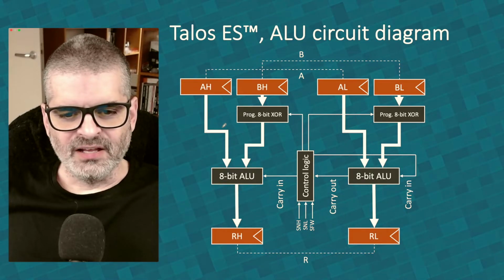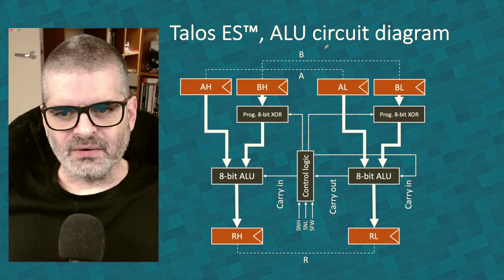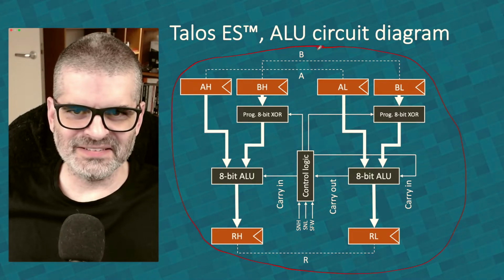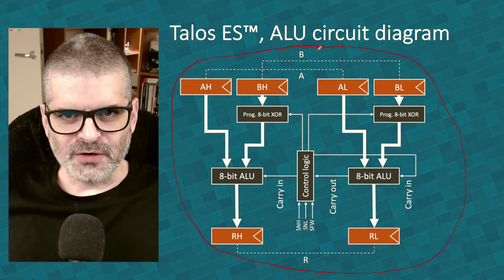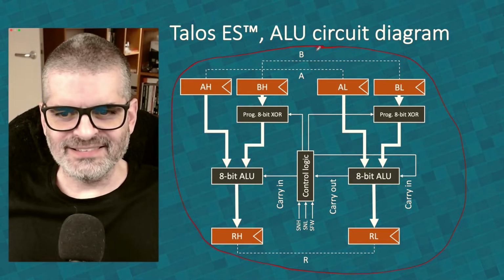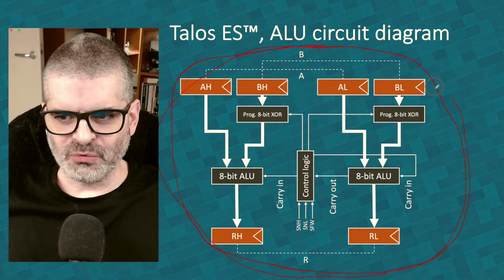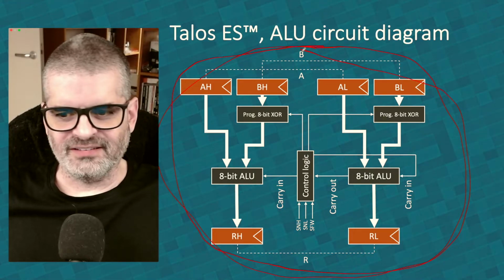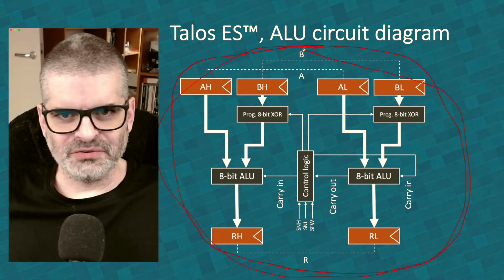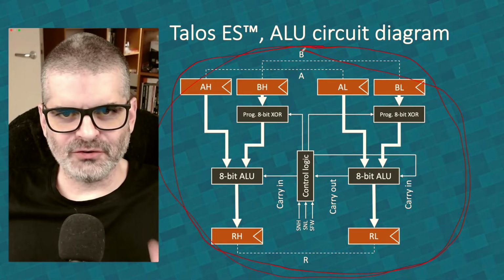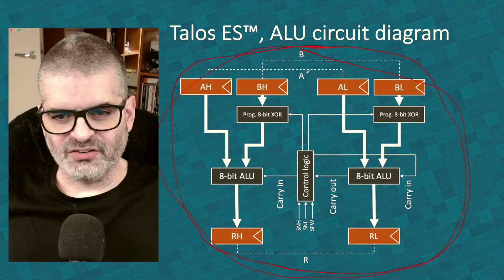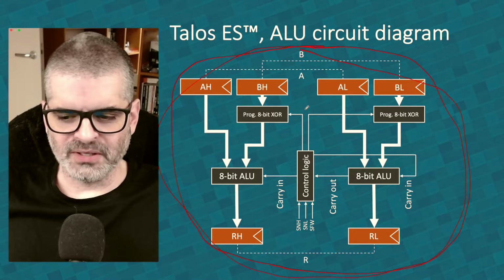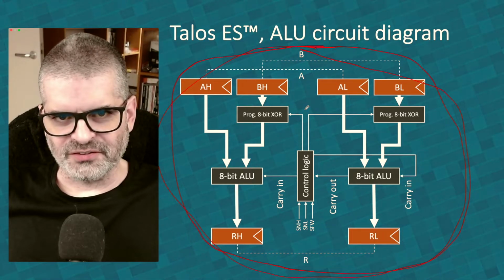That's the issue. So there will be in the final ALU card a lot more chips than there are blocks in this diagram, but you will know when you look at all those chips that in essence it's just this. It's just what is in here. Everything else is to deal with LEDs and keeping the current levels low and the voltage levels stable, or logic to do bus arbitration, which we'll talk about in a moment. In essence, it's just this, so it's pretty simple.